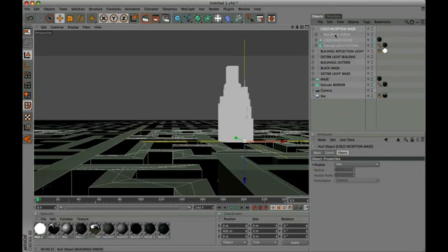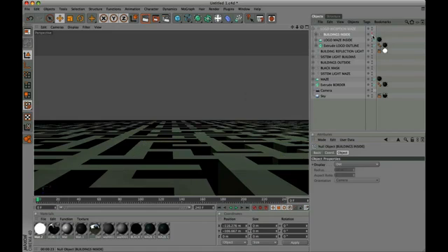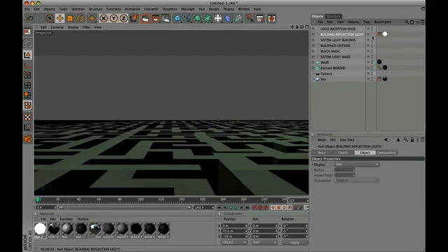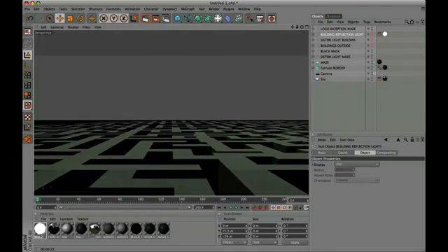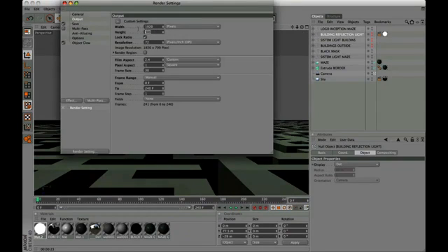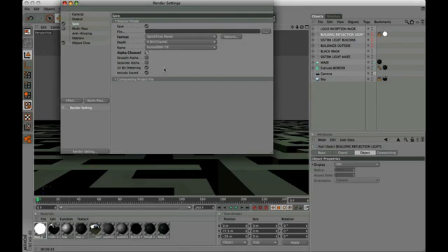Before, make a render of the complete maze without skyscrapers, with the system maze light active. Open the Render Settings panel, set the size 1080 and 450. We apply Alpha Channel. Save as maze.